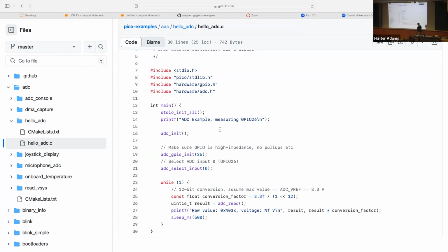Well, you have a couple of options. One option I would say is you could call ADC read, and before you use the result to, say, set the number of balls in the Galton board, shift out the least significant 4 bits. That decreases your effective range, right? Basically now what we're saying is instead of getting 12 bits of resolution for our ADC, we're getting 8 bits of resolution. So instead of numbers up to 4096, we get numbers up to whatever that is, 256, if I'm doing my powers of 2 right. But you'll get much less noise.